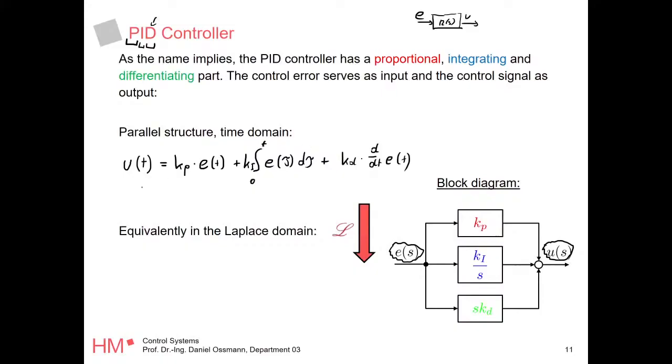So you can easily Laplace transform this. You know how to replace all of this, and what the result is. R of S is nothing but the output over your input, which in the case of the PID controller is, obviously, the input is the control error, the output is your input to the system.